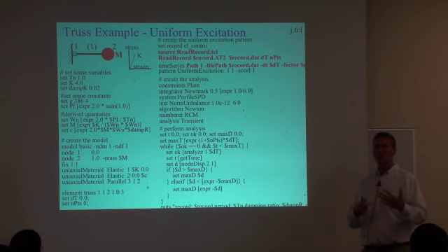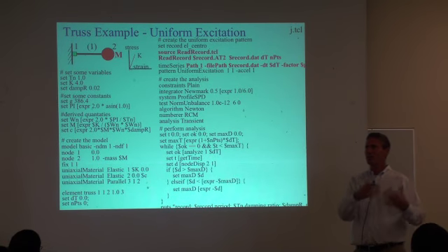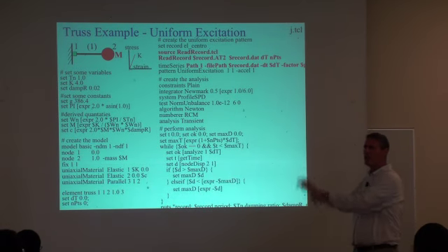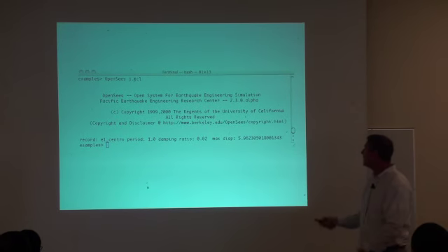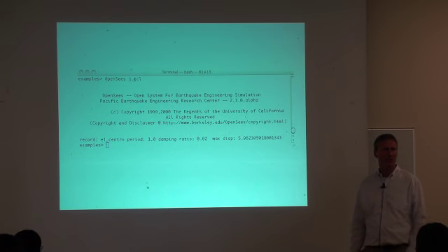But before you do it, you set it up to run once with, say, this period 1 as the motion. And once you've got it running, then you say, okay, let me modify it a little bit to take in variable arguments where I'm going to pass in the period. So I won't use the T n equals 1, I'll use the argument command. And I won't take, say, the record El Centro. The record will also come from the argument list. So this is set up for that. So again, I don't just run a j.pickle, I might run a j.pickle with a period and the particular motion. You set it up to do that when you're creating your script.